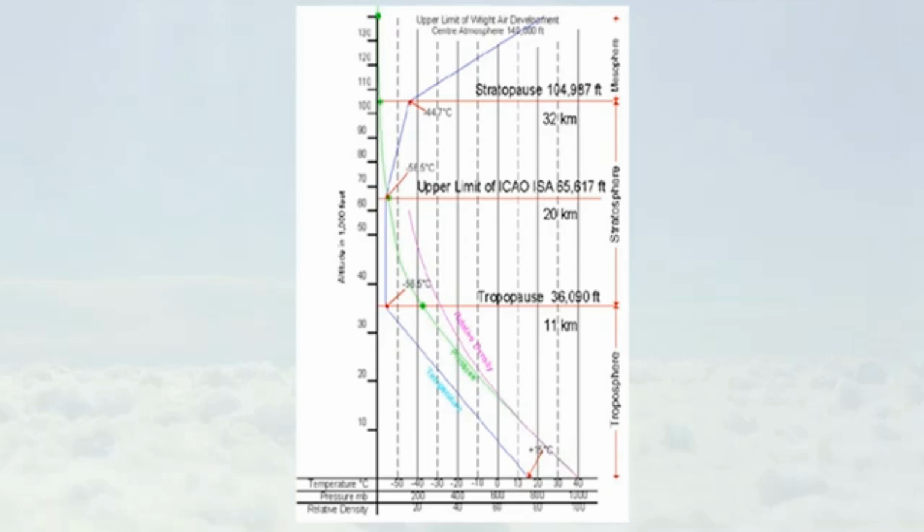Basically, the laboratory calibration consists of applying a series of pressures to the altimeter and checking that the instrument indicates the respective levels which correspond to these pressures in the ISA. Any discrepancies, if within certain agreed tolerances, would be listed over the operating height ranges as instrument errors.